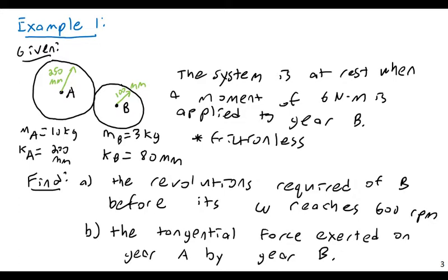Well, as a kid, you always wonder, what's the limit of this? How far can I take this? And there's a couple limits. One is, of course, friction. A very fast-spinning pulley or a very fast-spinning gear will have high amounts of friction. But the other is actually this force here, this tangential force. Yes, you can make one gear turn very fast or exert a great amount of force in the form of mechanical advantage if you wish.